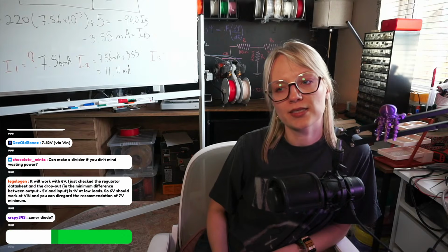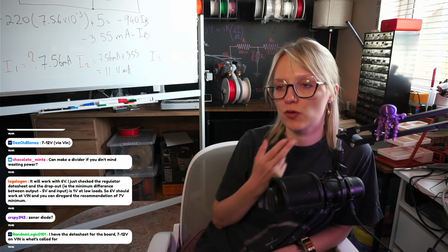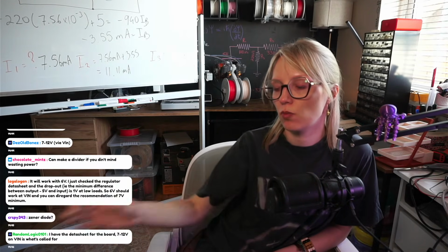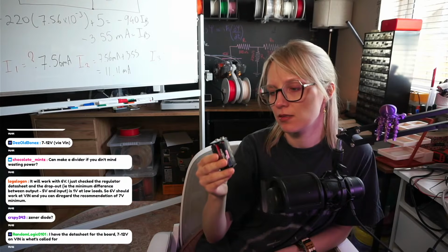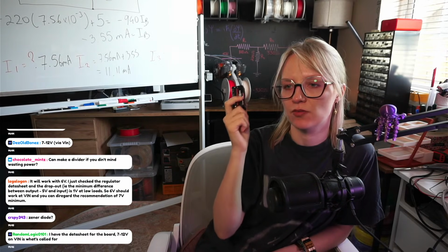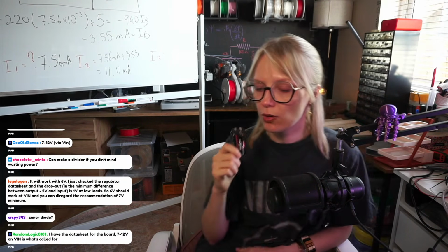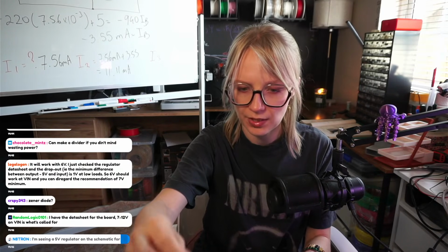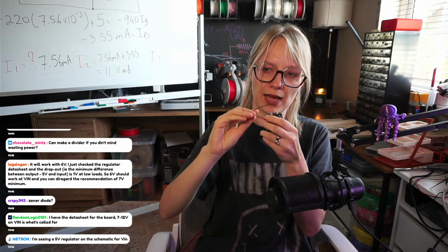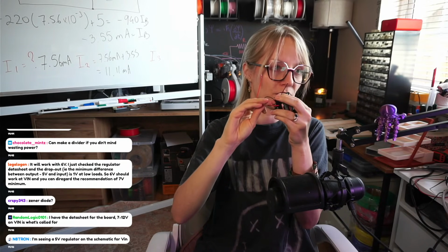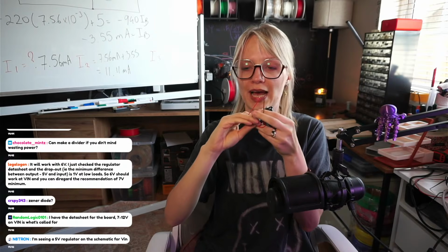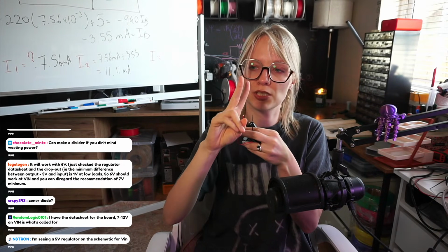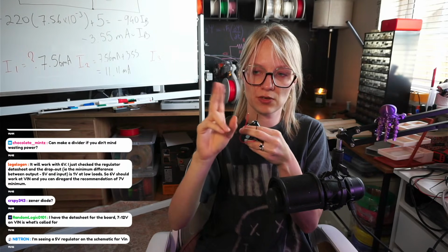The problem as well is that it needs to split between 2 Nanos. So they're obviously going to be in parallel, so the voltage is the same. But one battery pack that's supplying 6 volts like this. Is this 6 volts? Yeah, this is 6 volts, for example. We're going to have to split it with 2 wires. So we'll get something like this connected to it. And we have 2 wires like this. And we'd have to solder it to another little breadboard, a soldering board. We'd have to split dual into the ends and the grounds. And they'll all...